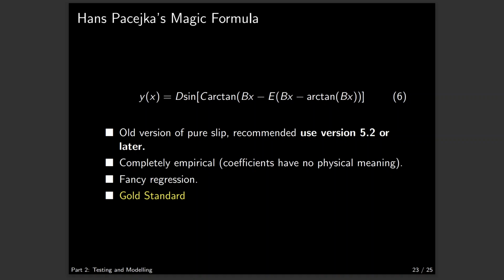This is essentially a type of regression curve, and it is important to know that we call this an empirical tire model. By calling it empirical, we mean that the coefficients in equation 6 have no physical meaning. Rather, they just change the shape of the tire force curve.